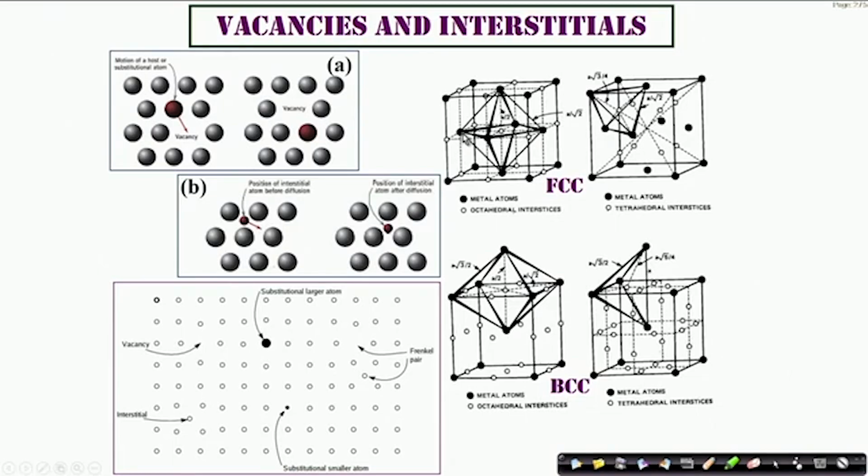But when you say that you expect atoms to occupy corners and face centering positions, then the centers of the edges and the center of the cube or center of the unit cell obviously are lying vacant, and the diameter of such vacant hole is the largest. So this is how you can actually define a possible interstitial vacant site and its size in an FCC crystal.